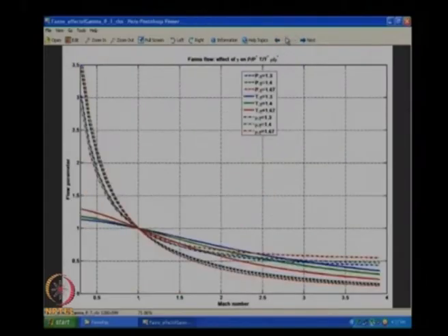Now if you look at the remaining curves, pressure, temperature and density, I will first show this one. This is the temperature, the solid lines are the temperature, and you can see this is similar to what we will expect out of any compressible flow. With more compressibility, you are going to have temperature variation in one particular direction. This is for any adiabatic flow. We saw a similar thing even for isentropic conditions.